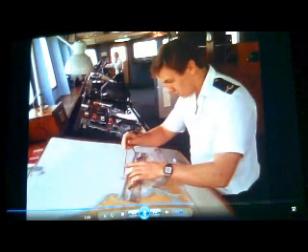Also, we will do rudder stack cycling. We saw the stopping maneuvers: how to stop a ship if the ship is going at sea with full speed, how much distance you are going to go, keep going ahead if you go astern, or if you turn in shallow water, turn in deep water. You will see all of this. We will do all of this today, quickly, one by one, so that you can cement your knowledge, or agree with what you have learned, that okay, this is what is going to happen.